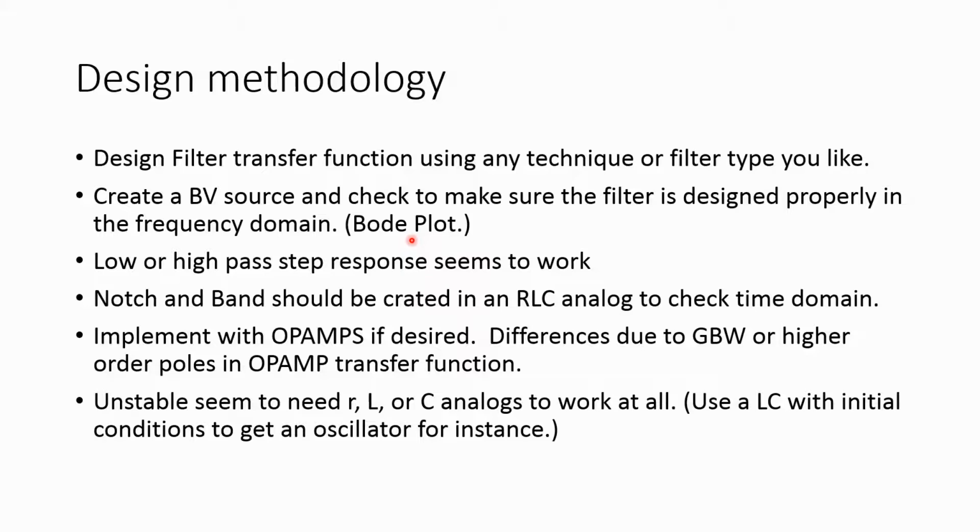Now to check it in the time domain, the low or the high pass response seems to work. So chances are, if you're doing a high or a low pass filter, and then you go into the time domain, it'll probably work. Notch and band, it looks like the overdamped responses deviate quite a bit.